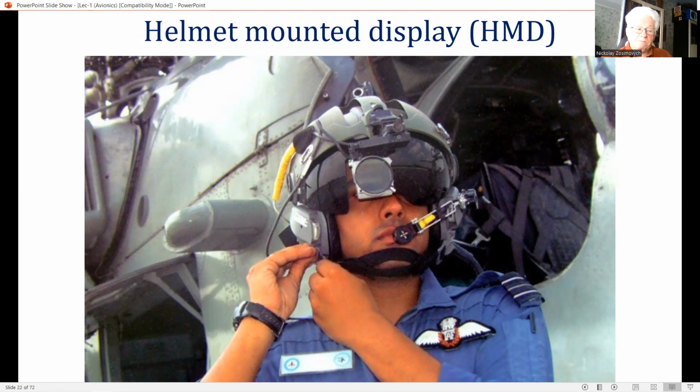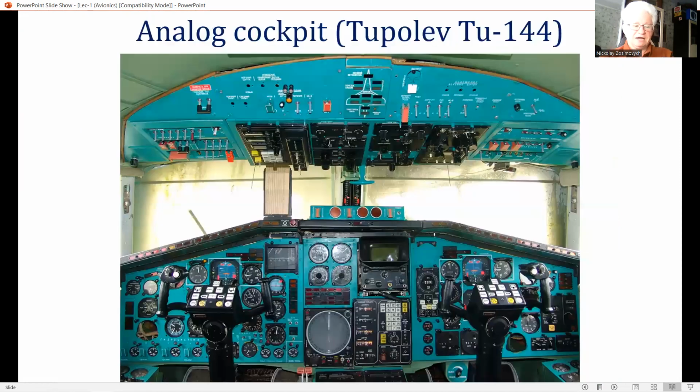These provide a complementary night vision capability, enabling the aircraft or helicopter to operate at night and in poor visibility. Color head-down displays have revolutionized the civil flight deck with multifunction displays, eliminating the inflexible and cluttered characteristics of the 1970s generation black dials with their numerous D-dial type instruments, displays dedicated to displaying one specific quantity only.